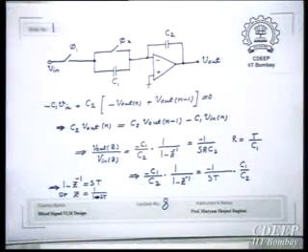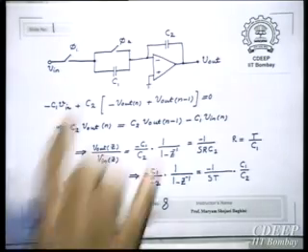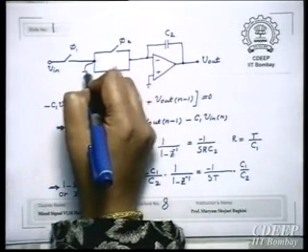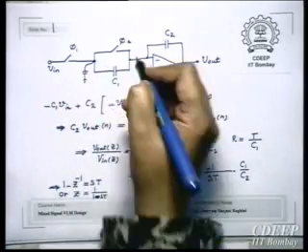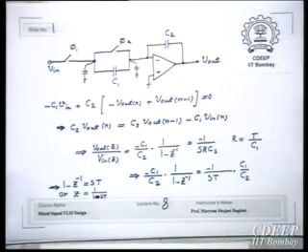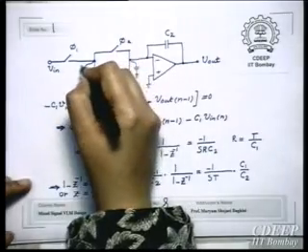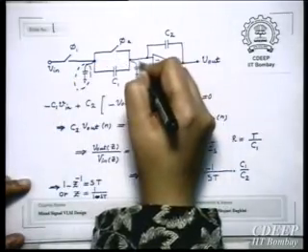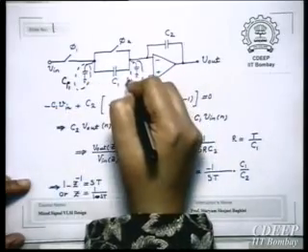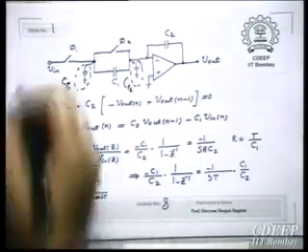So, this is the backward Euler approximation. One of the problems with these architectures is that the circuit is very sensitive to parasitics, because these switches are not real, are not ideal. Therefore, they will have parasitic capacitance. So I am showing parasitic capacitances in this way. Always you will have additional capacitances here. I am adding them here, but it's not a part of this derivation, I'm just showing parasitics. So these are parasitic.